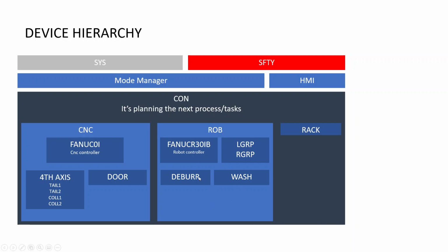You would just include those as robot outputs in this scheme. But that's not how I did it here. The left gripper and right gripper, two position devices that I have in the cell, are just monitoring the output state and the sensor state for each gripper, and issuing warnings and errors related to that.